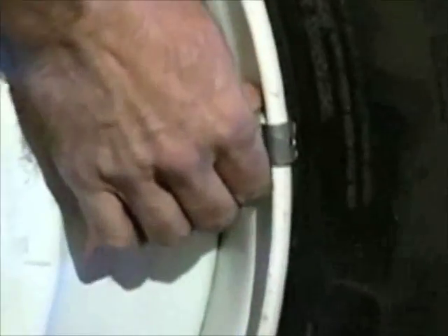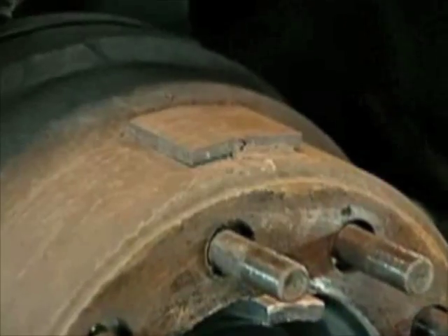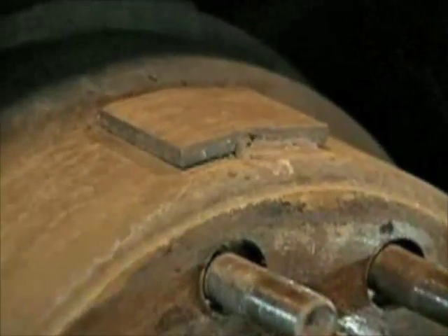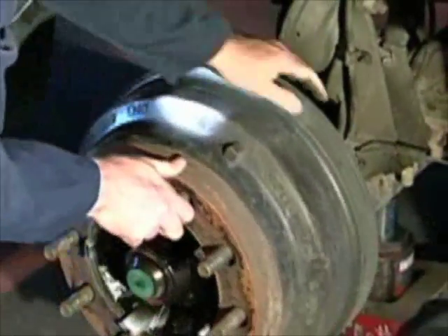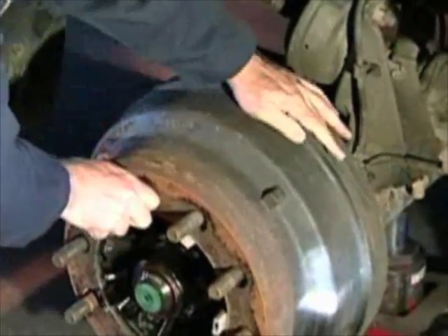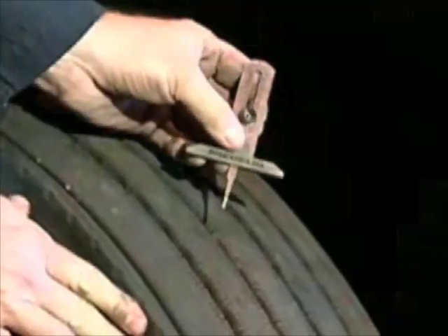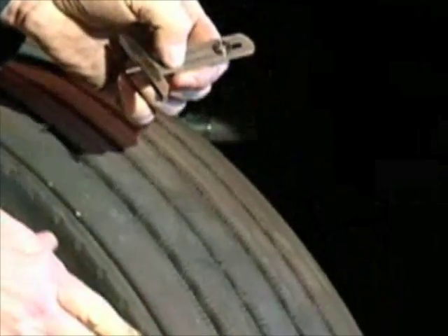Check the vehicle for worn front end parts, including kingpins, tie rod ends, wheel bearings, spring eye bushings. Check for balance weights greater than 16 ounces total. Inspect the inside of the wheel for old balance weights left on the wheel from a prior mounting. Check the brake drum for any missing balance weights. Some brake drum manufacturers grind off the heavy spot rather than applying balance weights. Therefore, no balance weights will be applied. On a used tire, check the tread depth in a centered tread groove in 4 locations circumferentially around the tire.